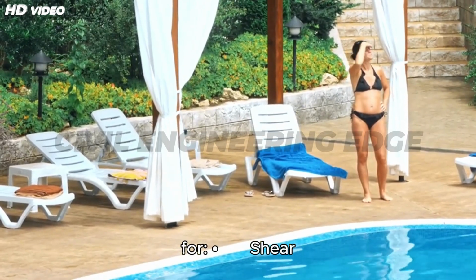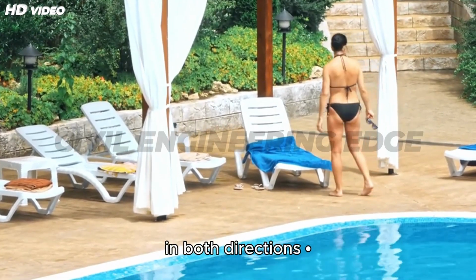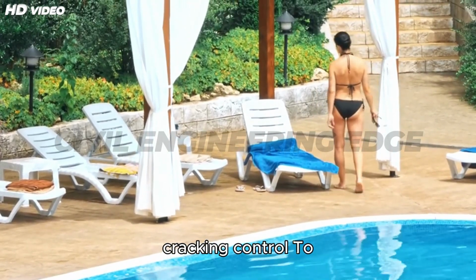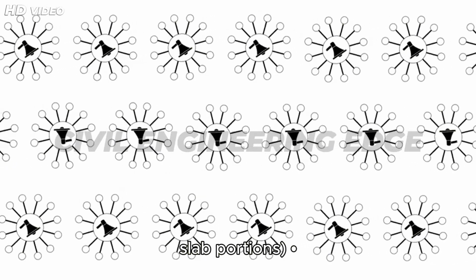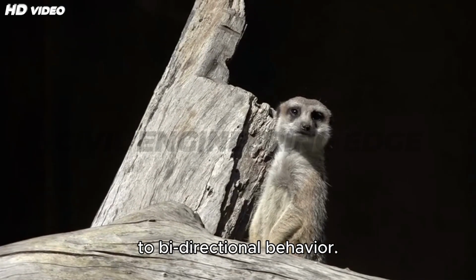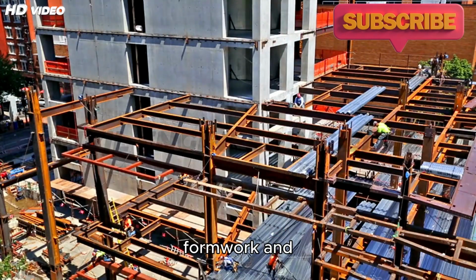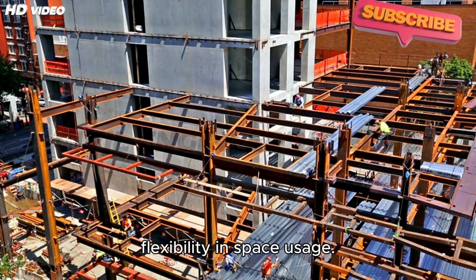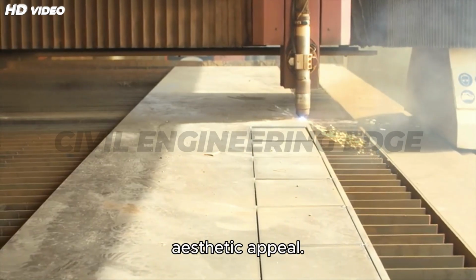Flat slabs must be checked for shear stress at critical perimeters, moment distribution in both directions, deflection and cracking control. To counter punching shear, designers may use drop panels (thickened slab portions), column capitals, and shear reinforcement. The reinforcement layout in flat slabs is more complex due to bidirectional behavior. However, the absence of beams allows for quicker formwork and construction, as well as flexibility in space usage. Flat slabs offer both structural efficiency and aesthetic appeal.